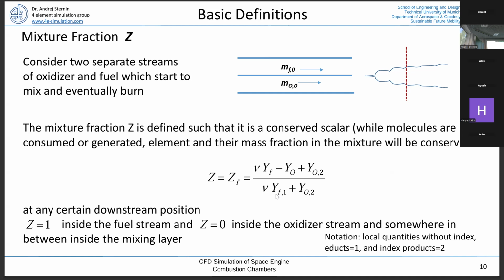We look at the mixture fraction, define where we have the stoichiometric mixture fraction, and here it's the most likely place where a chemical reaction takes place, because here we have locally the highest possible temperature in the system. A large number of models in combustion are basically trying to define the position of the stoichiometric mixture fraction, and this would mean that this is the position where the flame is sitting.